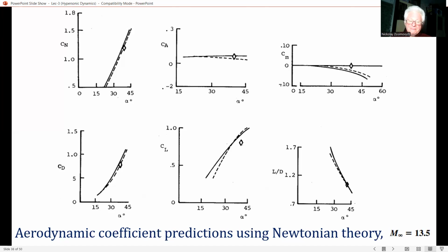For the most part, the HABP calculations are markedly close to the wind tunnel data over the range of angle of attack. The flight data given here are from STS-1, Space Shuttle 1, but some of the coefficients deviate slightly from both the wind tunnel data and the HABP calculation. But overall, we can see that HABP is a useful engineering prediction code for space shuttle aerodynamics.